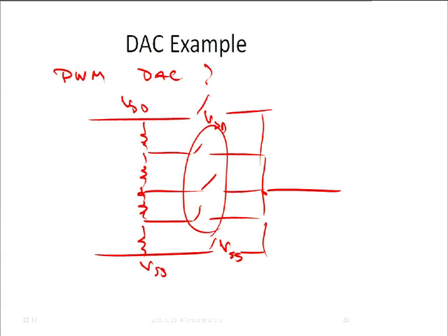Now, 256 isn't that terrible a number for an integrated circuit, no big deal, you can do that. When it gets to above 1,000, then it starts consuming so much area that other solutions become more attractive. But it's simple, and up to 8 or 9 bits, this solution is frequently used.